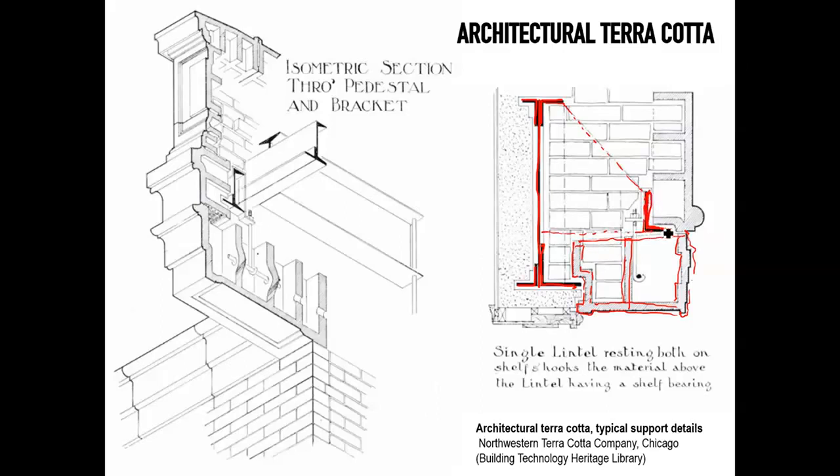And this angle is running continuously to then support this other terracotta element that comes up. It sort of engages with the bricks, etc. And it's giving some molding here on the outside. At the back of this angle, there's another angle you can see here with a J-bolt.